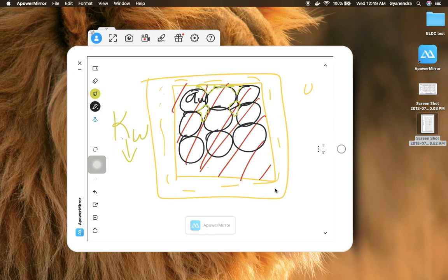Generally, for a single winding inductor, for initial design you can choose 0.6, to be on the safe side that the windings will for sure fit into the window area. People have gone beyond that, up to around 0.95, but those are professionals.